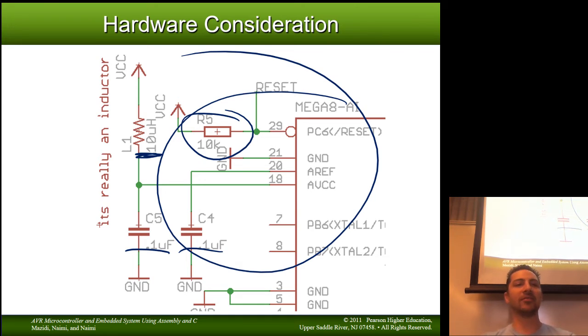As a convention, however, people don't sell 100 nanofarad capacitors. They either sell something in the picofarad range or the microfarad range. They will sell you a 10,000 picofarad capacitor, but they won't label it a 10 nanofarad capacitor. For whatever reason, they label them in picofarads or microfarads, but not nanofarads. Something to keep in mind if you're ever looking for a capacitor. Why won't they sell me a 100 nanofarad capacitor? Look for a 0.1 microfarad capacitor and you'll find it.